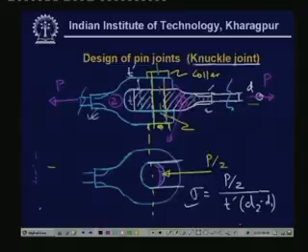So, if you look at any of the standards in a good design handbook, you see that those dimensions, that is the curvature of this I bar, of this fork end, are related to the measured dimension D. So, this is how normally those things are to be selected.